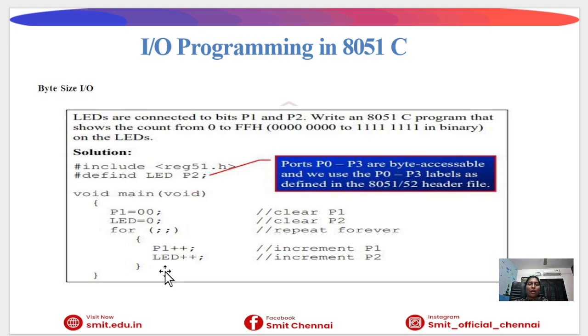Now, the delay is not always exact. There are three major factors that affect the accuracy of the delay. First, in the 8051 design itself, the 8051 executes instructions in terms of machine cycles. Each machine cycle consists of a fixed number of clock cycles.